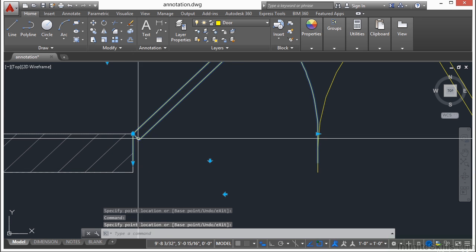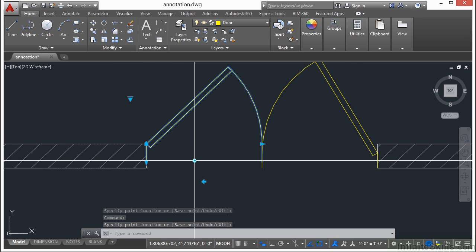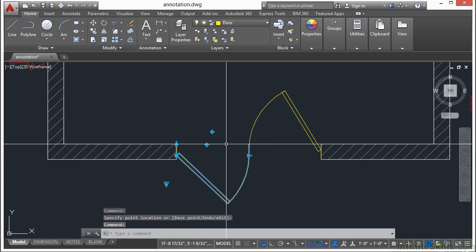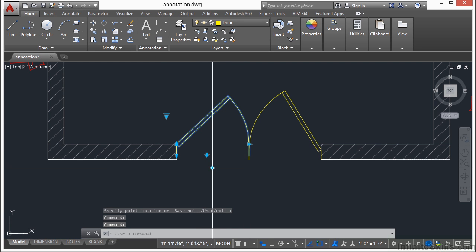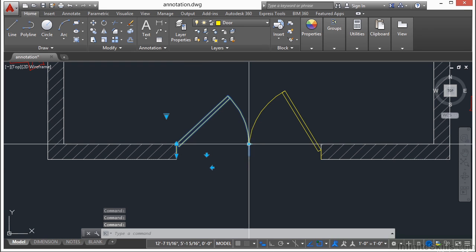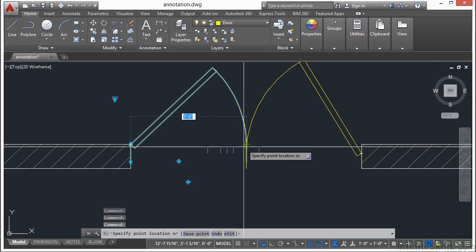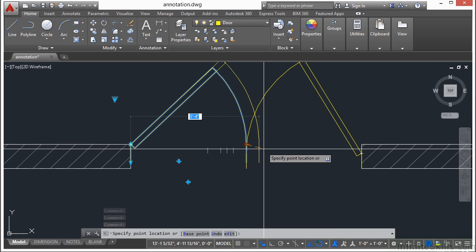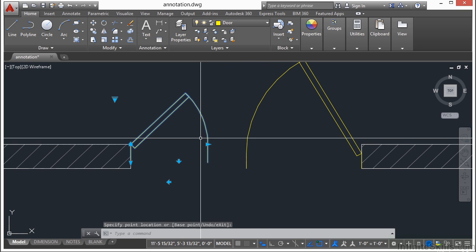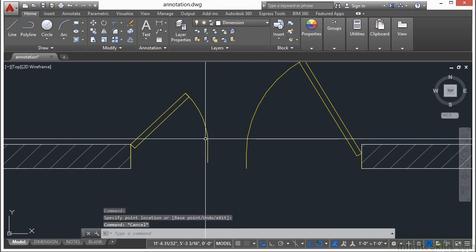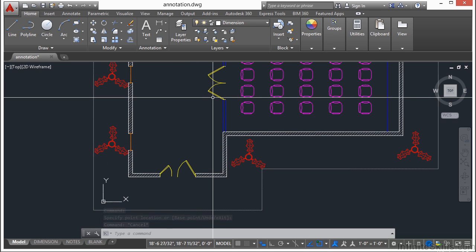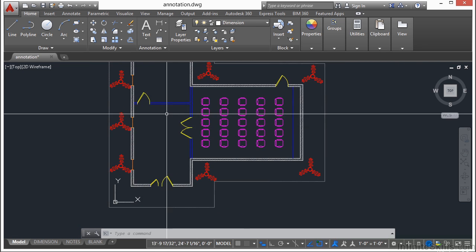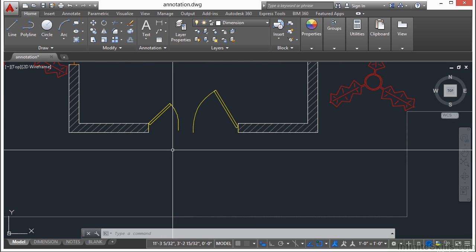It acts sort of like the standard move. This button here will set the direction of the swing. It opens in or it opens out. It's a toggle switch. This is very similar. This will move the door in or out. And then this grip here will change the width of the door. I can stretch it out to 3 foot 4 inches or all the way into a very tiny door of 2 feet wide. Just press escape to let go of that. All of these door block instances that you see here are the same block. It's very useful and helps in your design process.